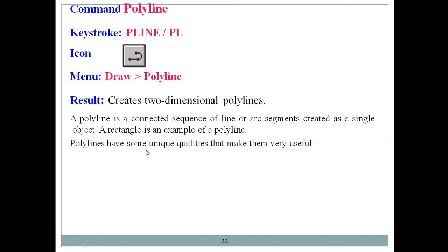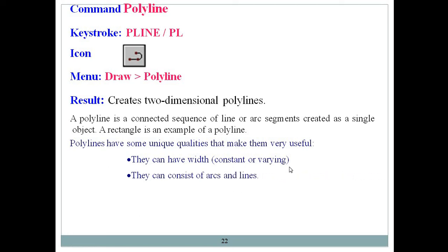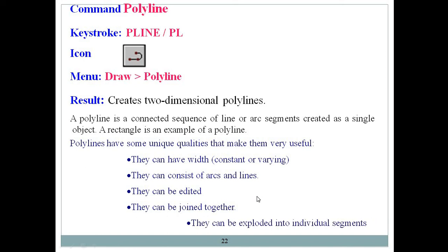Polylines have some unique qualities that make them very useful. They can have width, constant or varying. They consist of arcs and lines. They can be easily edited and joined together. Also, they can be exploded into individual segments. This is the polyline command.